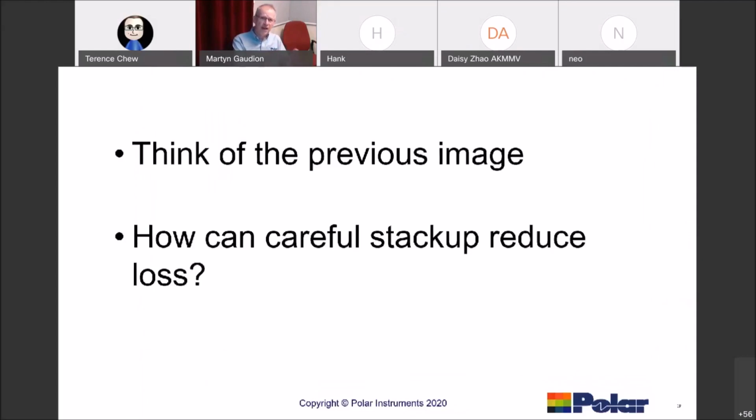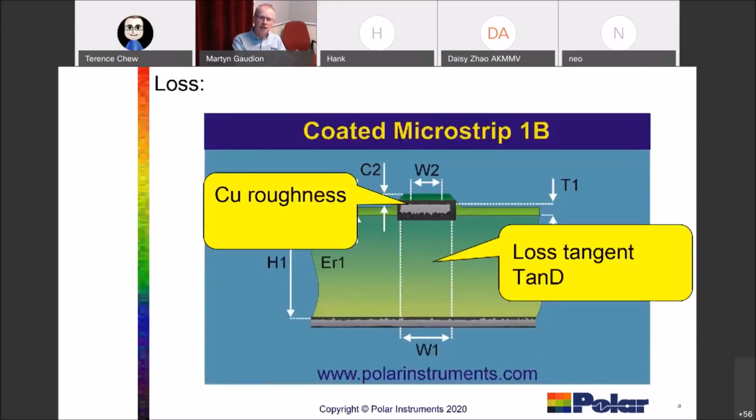So I'm going to go back to that slide again, and think about this. You've got the roughness here and here. Typically, if this is a core material, that's for a controlled impedance, you'd normally fabricate the critical traces across the core, and you've got a rough side here and here. But if your copper had the rough faces on the inside, you could stack across the other way.